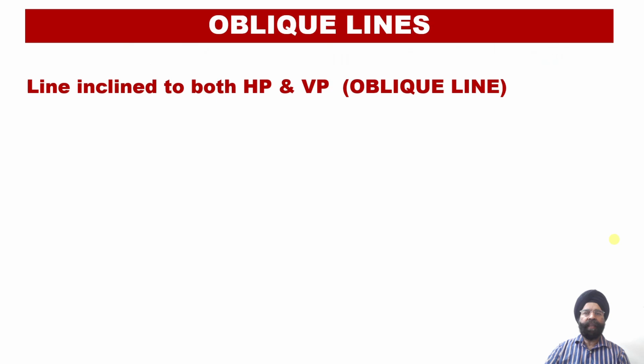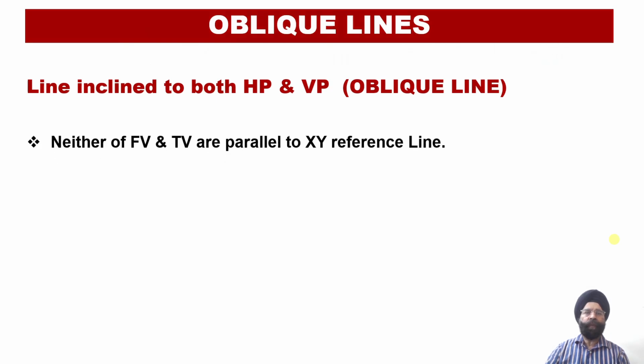An oblique line is the one which happens to be inclined to both the reference planes, that is the horizontal plane as well as the vertical plane. Now, due to the inclination of the oblique line with the two reference planes, neither the front view nor the top view will be parallel to the XY reference line.